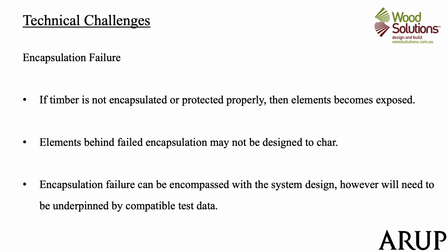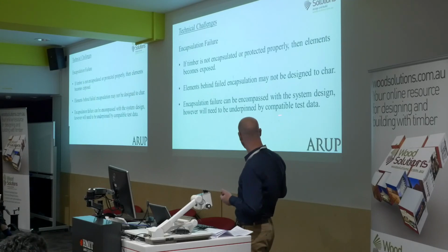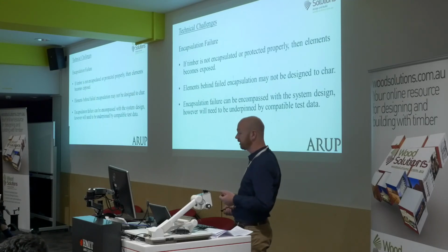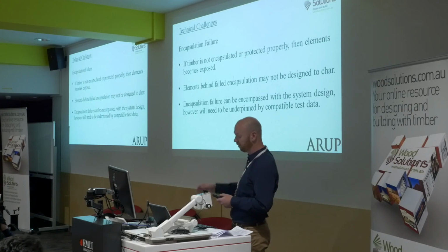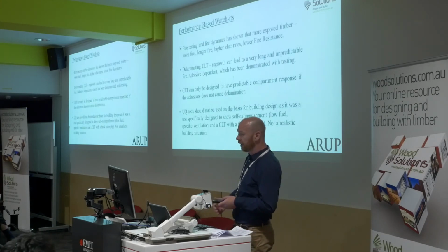Encapsulation failure can be used as part of a performance-based design, as part of a system, where you partially rely on the encapsulation, then partially rely on the charring of the wood, but this really needs to be underpinned by compatible test data. You need to be very sure when your encapsulation is likely to fail.